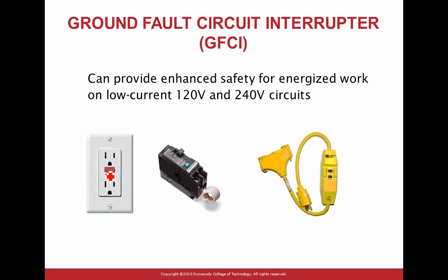So that's your equipment. GFCI protection, guys, can also protect you from a lot of things. Like I said, you are an exception because you have a process. But if you can use GFCI for your equipment, you should use it because it provides extra protection from the shock hazard for people.